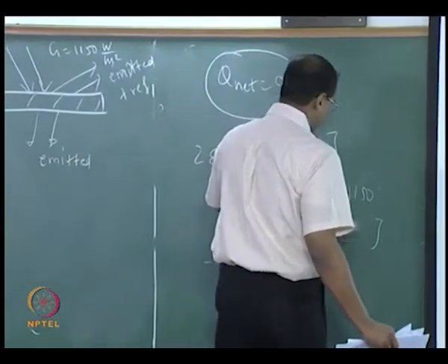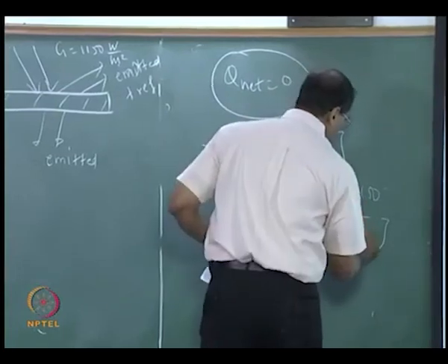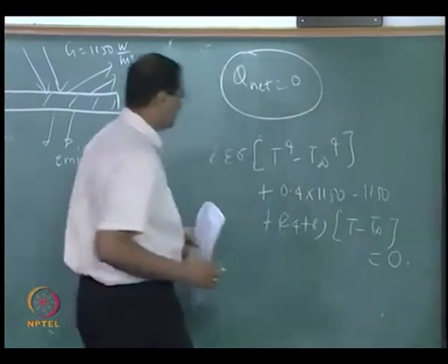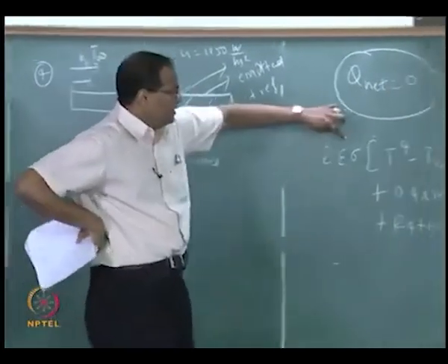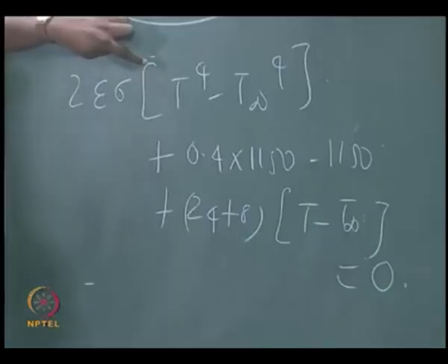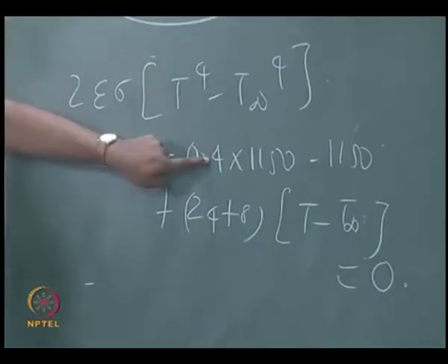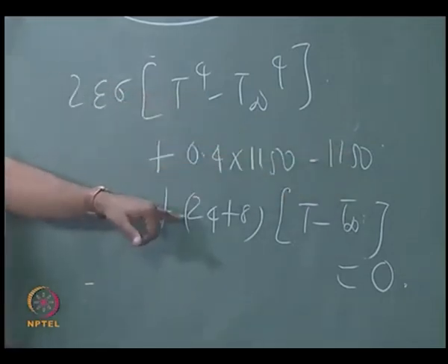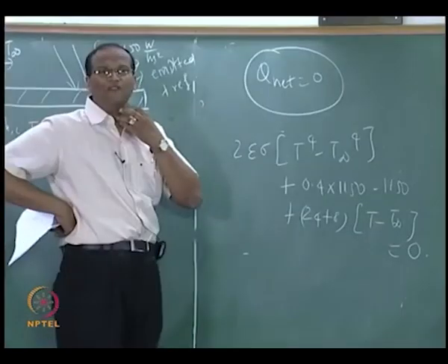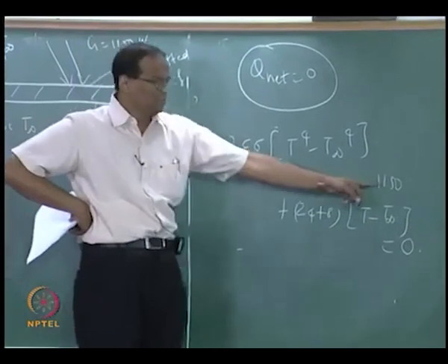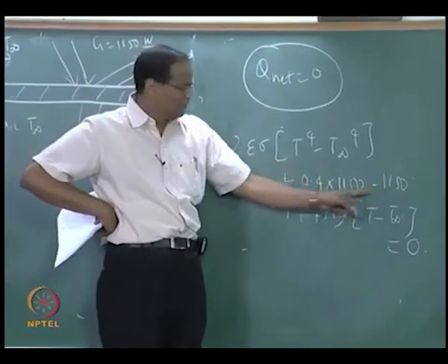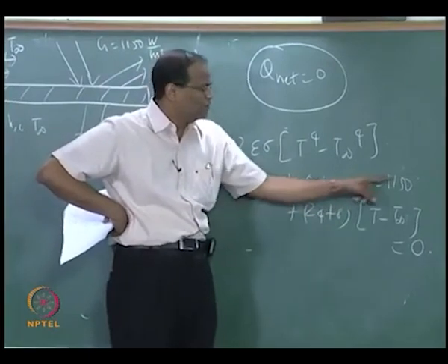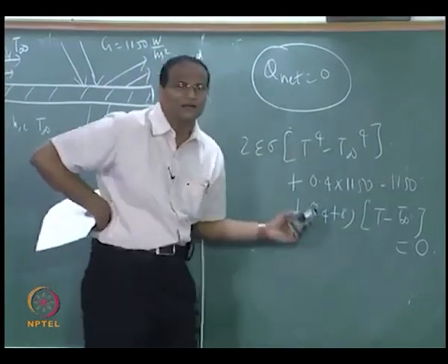I will just put T infinity first equal to 0. The net emitted plus whatever is reflected minus whatever is incident plus whatever is convected must be equal to 0. If everything is going, where is the source? The source is this minus 1150. Rather 0.4 into 1150 minus 1150, which is nothing but...